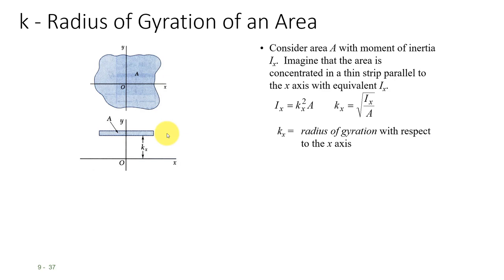So if you get the radius of gyration, instead of r squared A or r squared m, you plug in that radius of gyration, and it's not really that the mass is there, but it feels like all of it is piled up at that radius. And it's not the same as the center of mass, and it'll be just something that is given to you. If you calculate the inertia and they ask for the radius of gyration, you can get it: square root of I over A.